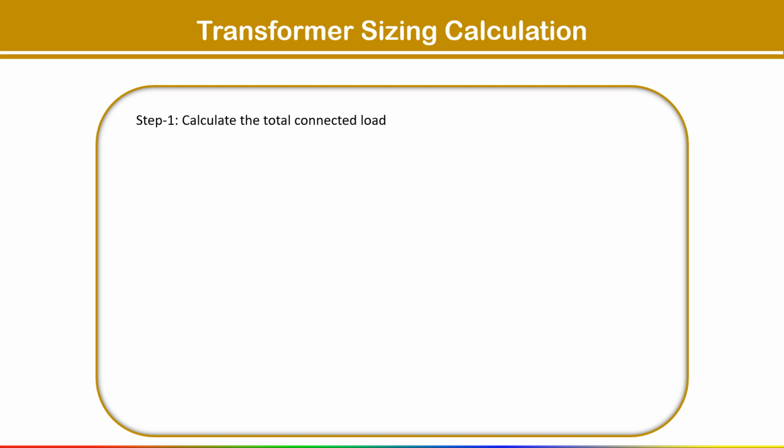It encompasses all devices, appliances and equipment that are simultaneously connected and drawing power. These include lighting, heating, cooling system, machinery, appliances and any other electrical device in a facility. The connected load is essential for sizing electrical infrastructure such as transformer and distribution system, to ensure they can handle the total power demand.